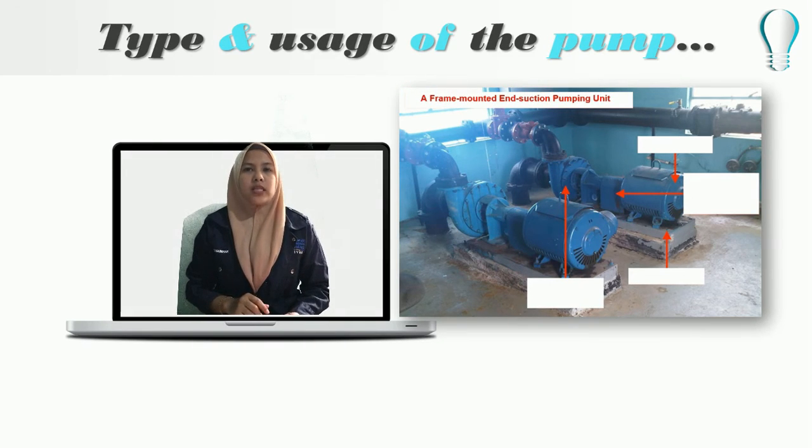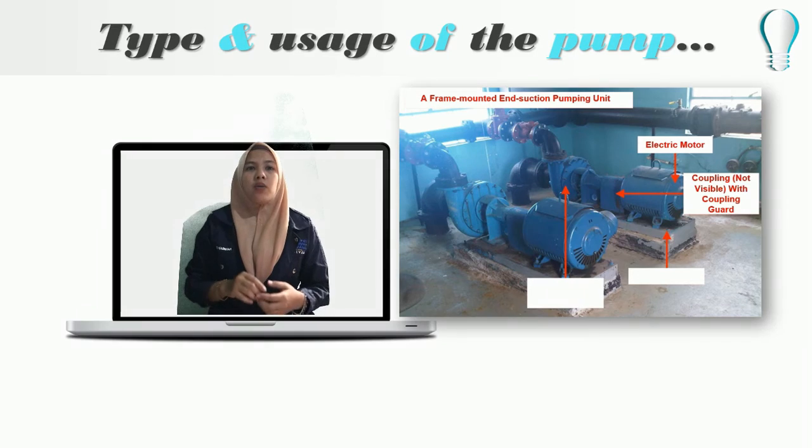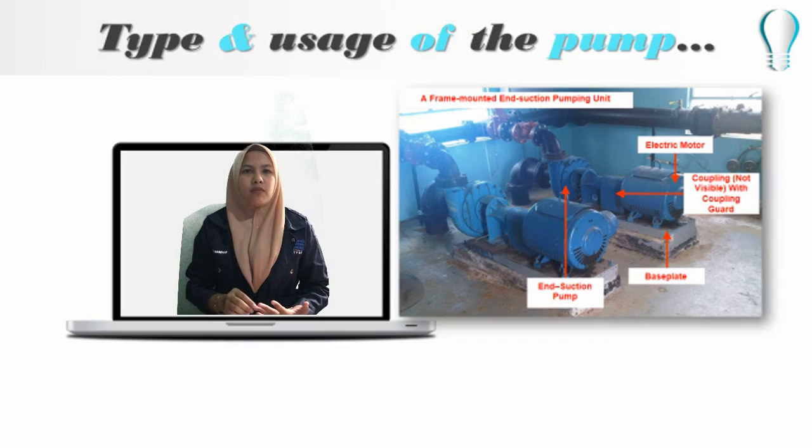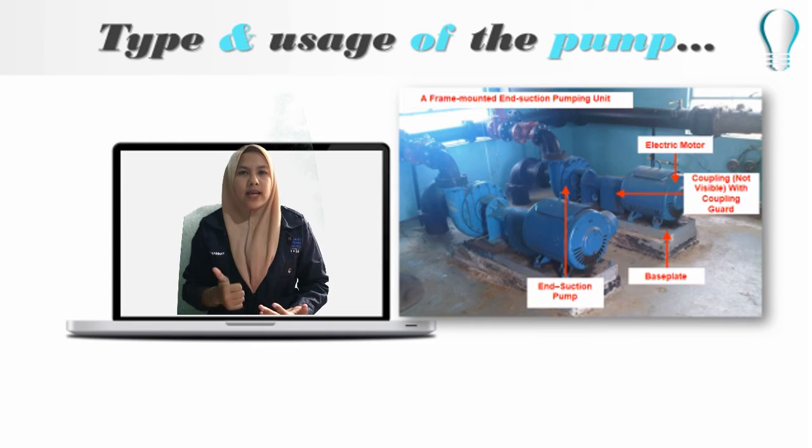One particularly popular specialty end suction design is the submersible pump. The submersible pump is an end suction design that has been fit with a motor designed to operate while submerged. This allows the entire pump to be submerged in the liquid being pumped. End suction pumps, such as the submersible, which have been designed to handle solids, are often fit with mixed flow impellers or specialty impellers such as the vortex or screw impeller. These specialty impellers are designed to handle solids without clogging.